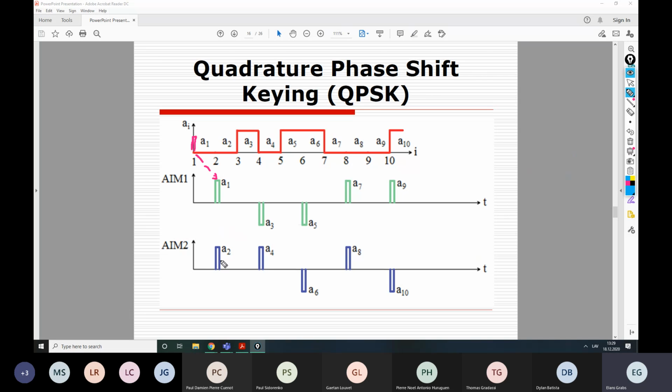Right? The next thing, actually let me mark that with green so that it would be more clear, right? So this is green one. And the second symbol happens at the same time moment, but it's not delayed, so it comes to the AM2 at the same time moment. And these two symbols now are arrived at the same time, right? So as I told you, we are using NRZ, meaning that 0 is converted into +1, which is the case here, and 1 is converted to -1, which is, for example, this one, right? -1, -1, -1.